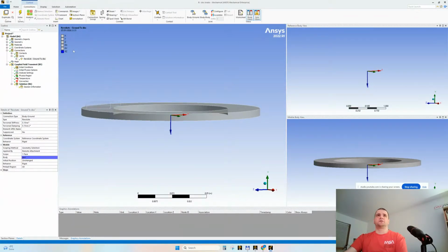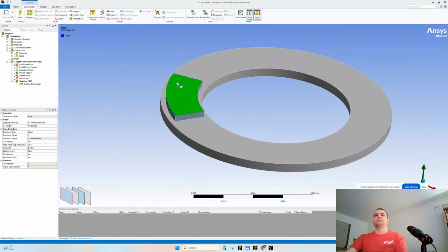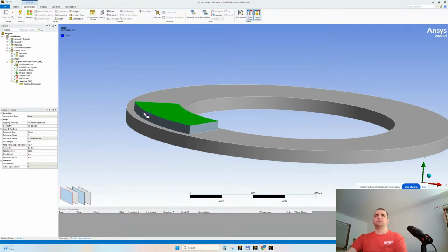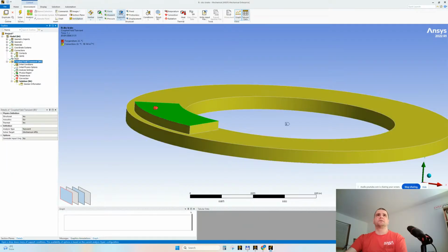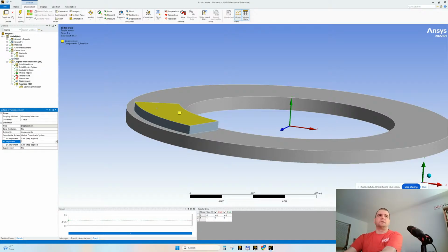And because the rotation is above the z-axis, we are correct. Then we're going to press the pad onto the disk. How much should we press it? Displacement, this is 0 and 0, and we'll displace it only with minus something, I don't know, minus 0.025, all right?